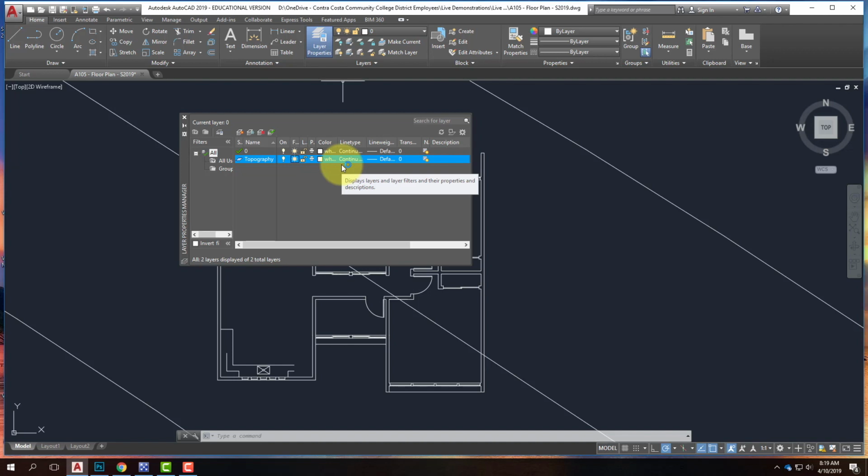Computers weren't as powerful as they are today. The truth is, we can do line drawings all day long on these computers, and it's never going to bog down. We can have giant files. It's never going to get slow because it's relatively simple. Back in the old days, it was really hard on the computers to do these kinds of line drawings and to keep really big drawings organized. And so AutoCAD, or Autodesk, the makers of AutoCAD, developed a twofold system, an on-off and a freeze-thaw. And the difference is that on-off just chooses to display or not display something. But that something stays in the computer's memory. So you're showing it or you're not showing it, but it stays in the computer's memory.